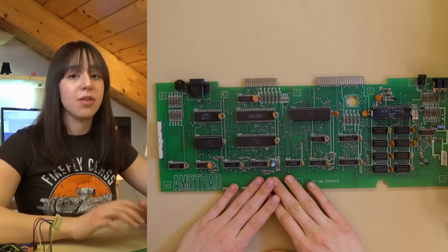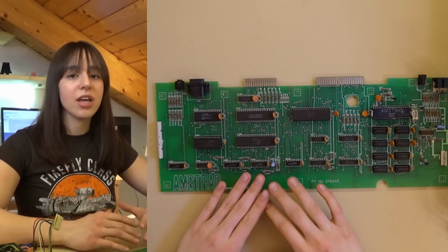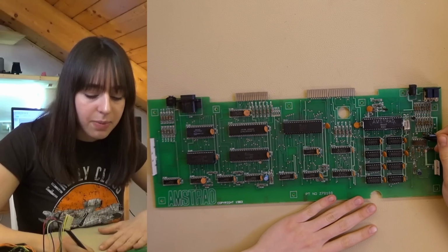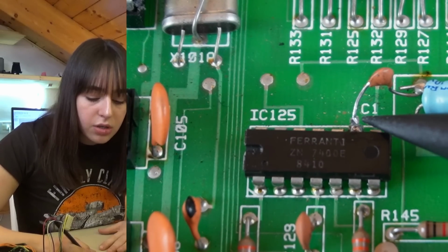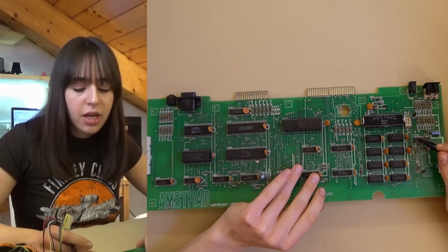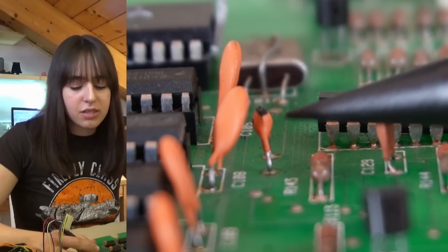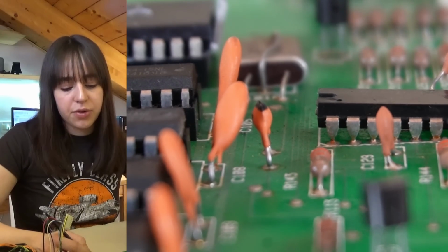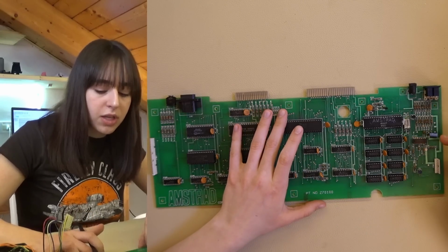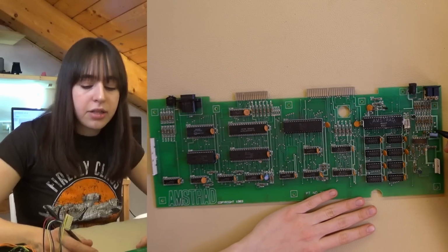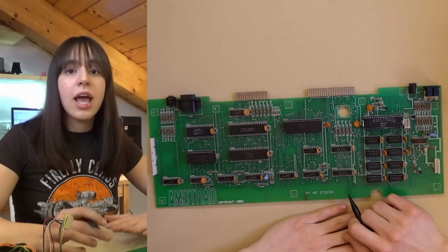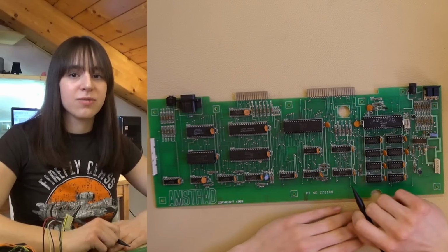Now I'm going to clean the board and then I'm going to check if it works. While I was cleaning, I noticed that this capacitor came loose. And also this component is soldered oddly, as this part is slightly raised compared to the other, but it seems like it's not causing any trouble making contact. So I'll add some new solder to the capacitor, so I'll reconnect it, and then I'll test if it works.